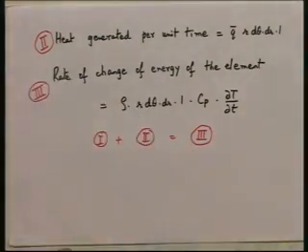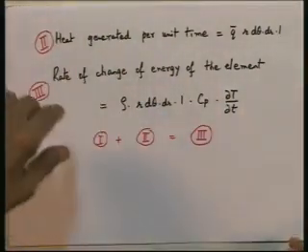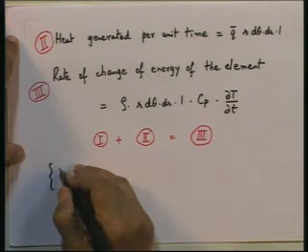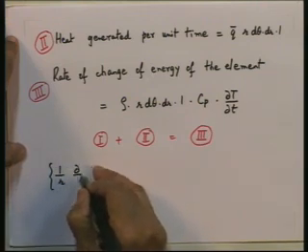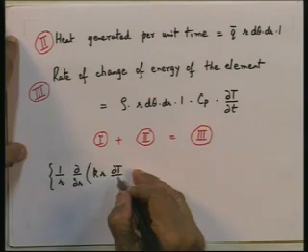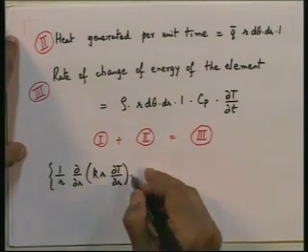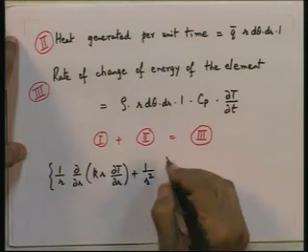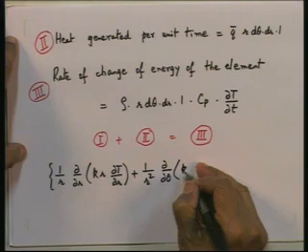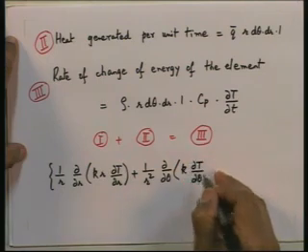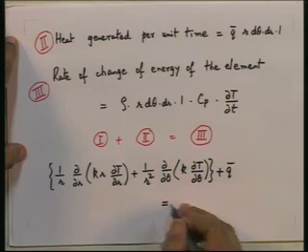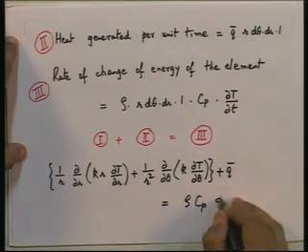So, we get the differential equation after clean up a little, cancel some terms: 1 by r d dr multiplied by k r dt dr plus 1 by r squared d d theta multiplied by k dt d theta plus q bar will be equal to rho Cp dt dt.